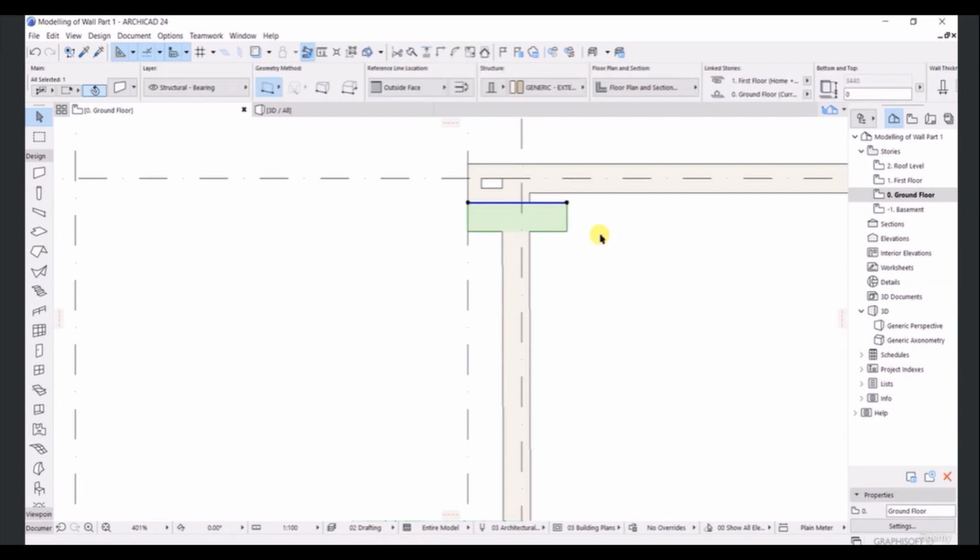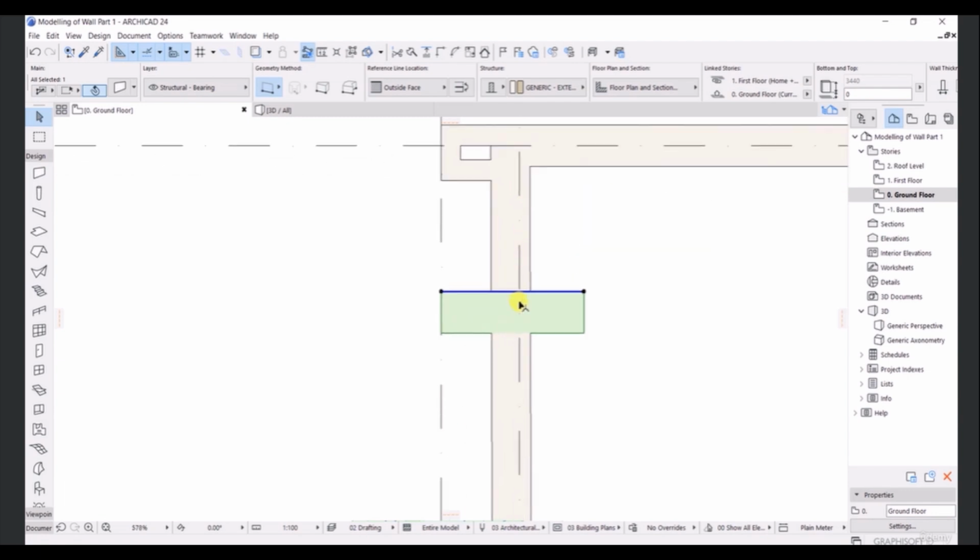So I'm going to go to this mode here. I will select this wall here. And after that, what I will do is I will Control D and I will select this one and I'm going to drag this one here. So let's enter the 800. Let's simply hit enter. So we have just moved this wall in this direction. Okay, so now after that what you have to do is you have to again simply enter Control D, and this time we are going to copy that one.